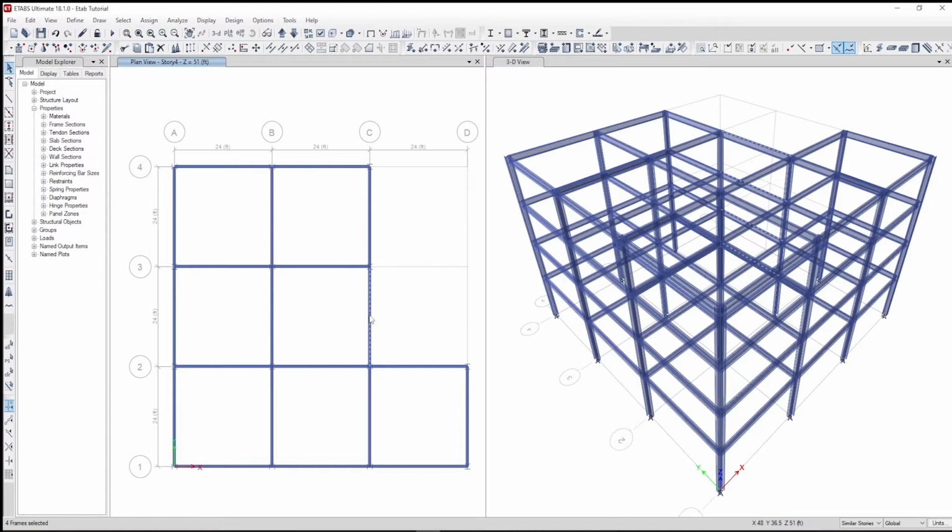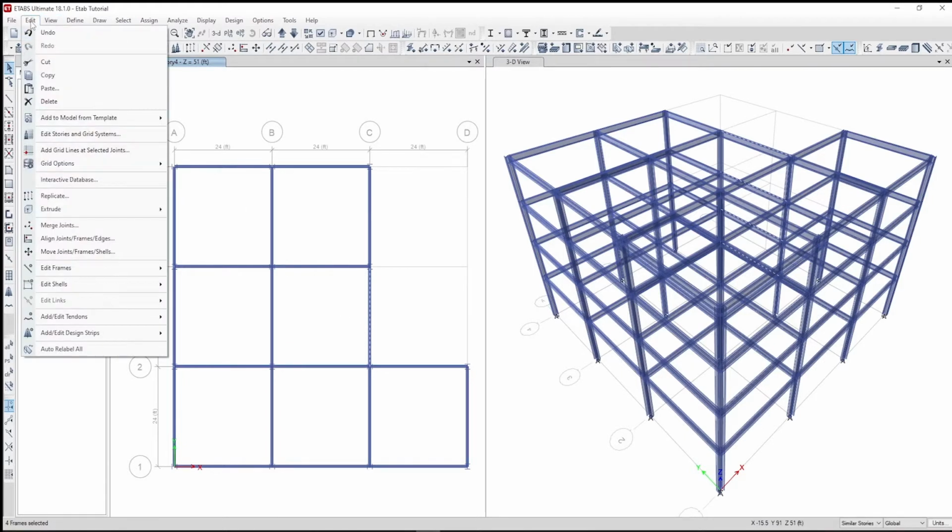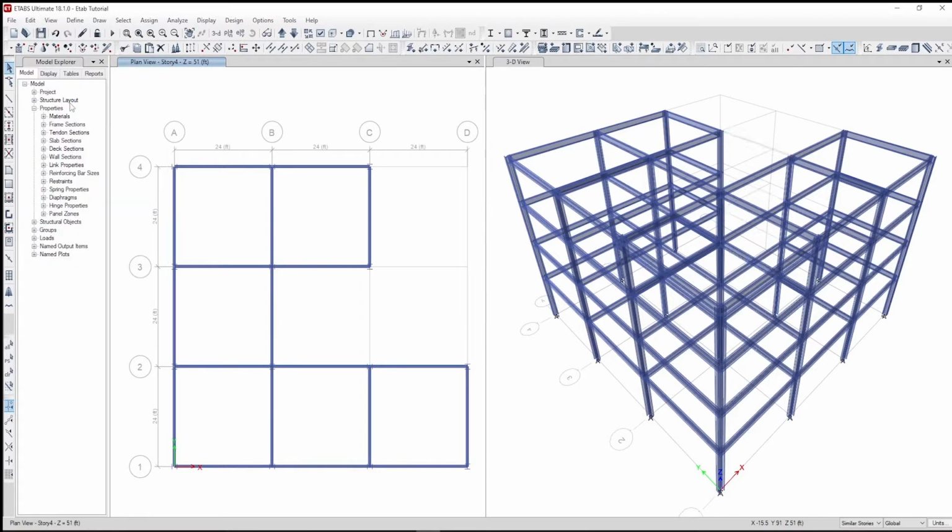In this model, we do not want the beam extending from column C2 to C3. To delete this beam, we'll select it and use the delete icon as illustrated in the video. To draw the composite beam, ensure that the A-Comp BM is selected in the tool properties. Make sure that the approximate orientation item in the properties of object form is set to parallel to Y.